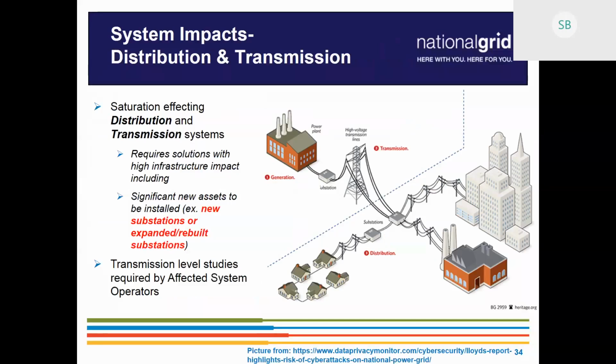that in a very small geographic area, which is where everyone wanted to interconnect, requiring new substations and rebuilt substations. In some cases, we're looking at even different distribution voltage classes to be able to physically get out to the sites where everybody wants to connect, and with higher voltage and higher capacity, we could potentially accommodate more. But those are the distribution side solutions. So from my group, we are looking at the Mass Electric MECO distribution solutions for what would have to happen in those areas. There is a dividing line between distribution and transmission.